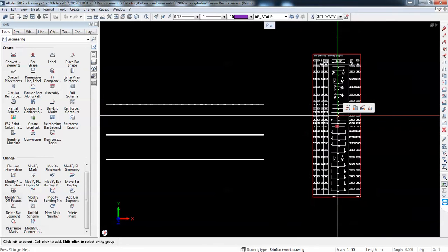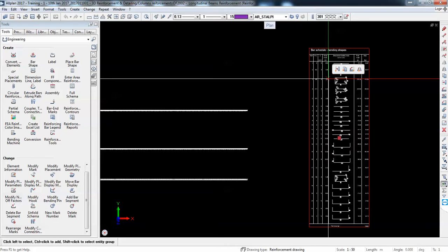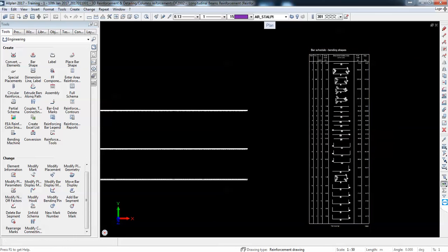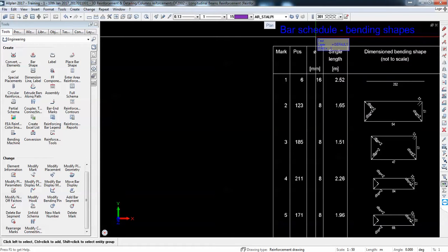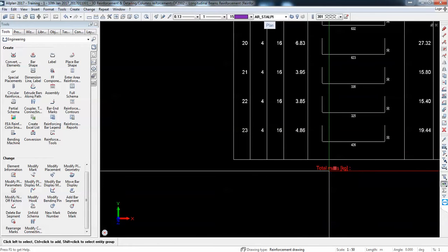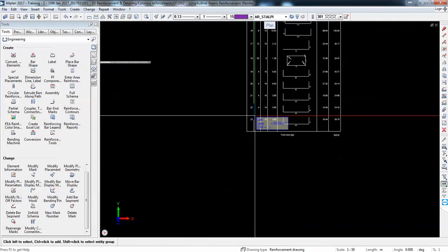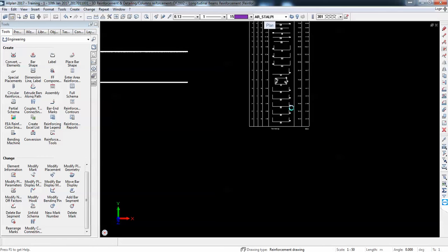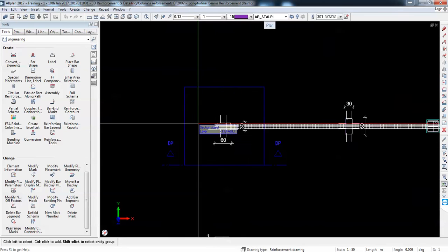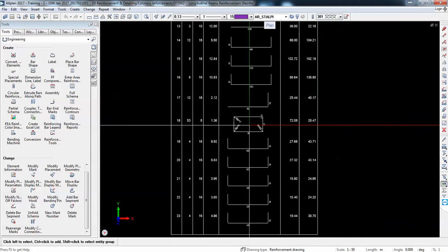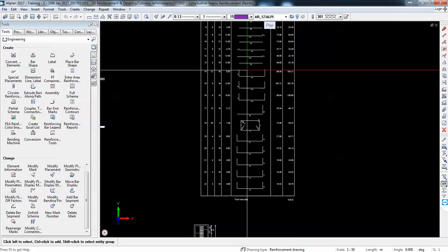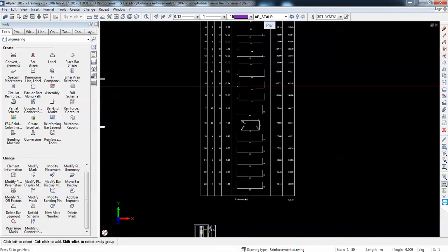And what I said was also not to keep them live, because look, if I right click and say ungroup, it will explode into a 2D construction, which of course is flexible, it's editable. And now if I do the same trick, I activate the column with its reinforcement, it's actually no problem. My report is not affected. Of course, my report is dead, it's not live.